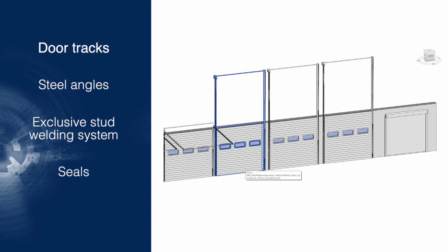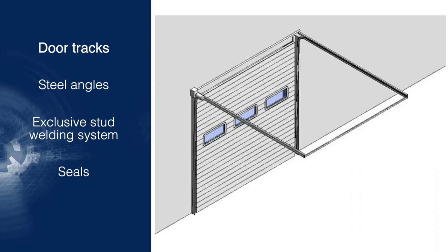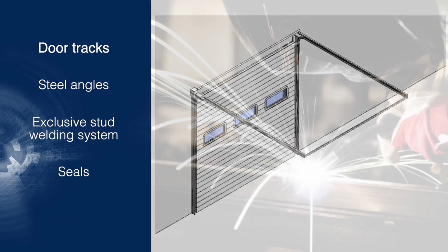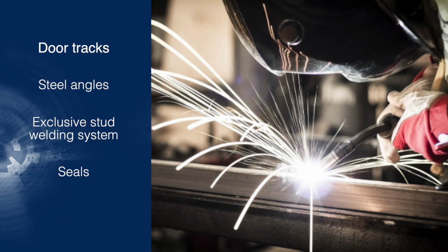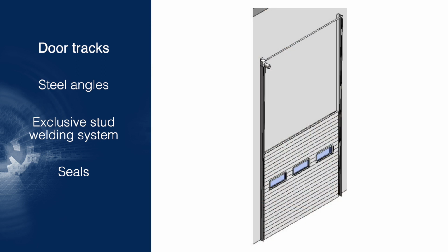The tracks require no on-site adjustments. Furthermore, all doors are equipped with cable brake devices to meet CE marking requirements. To achieve an optimal on-site installation, each sectional door guide track is custom manufactured to accommodate the specific site conditions, considering variations in headroom and roof pitch that may differ for each installation. Every sectional door is designed with seals along the outer edges and intermediate panels, ensuring a superior and durable weather seal when all fixing surfaces, floors and lintels are flush and square.